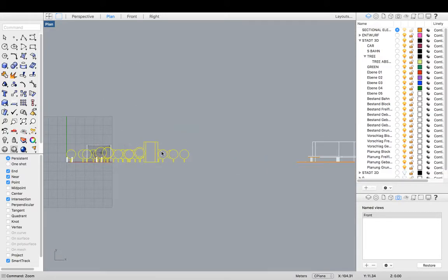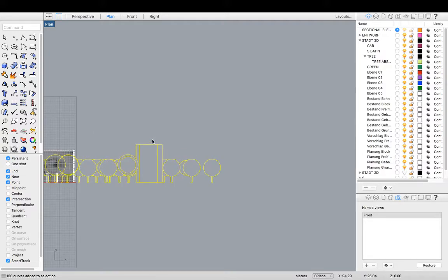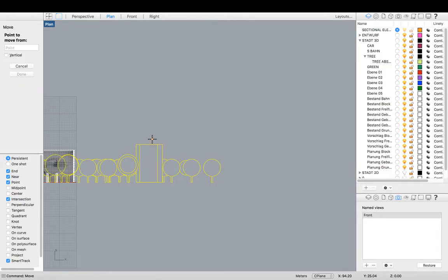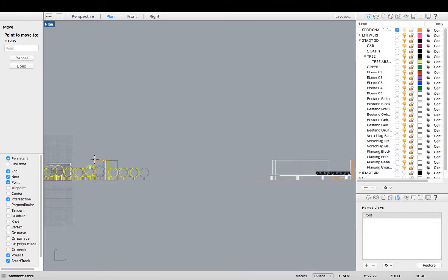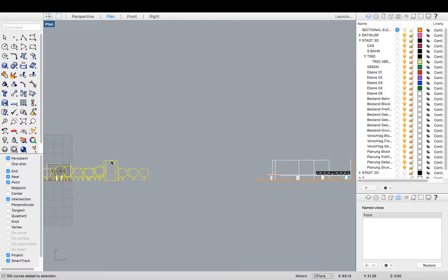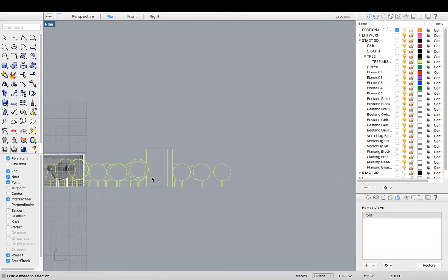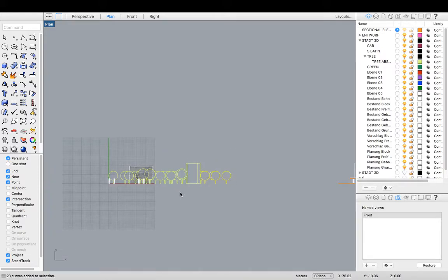This time, group again the objects, the trees that you've made. So now they're grouped, and we're going to move that with our project on from this reference point. We can actually delete that building. That would make it a bit easier. Ungroup those objects. I just don't want to duplicate that line.